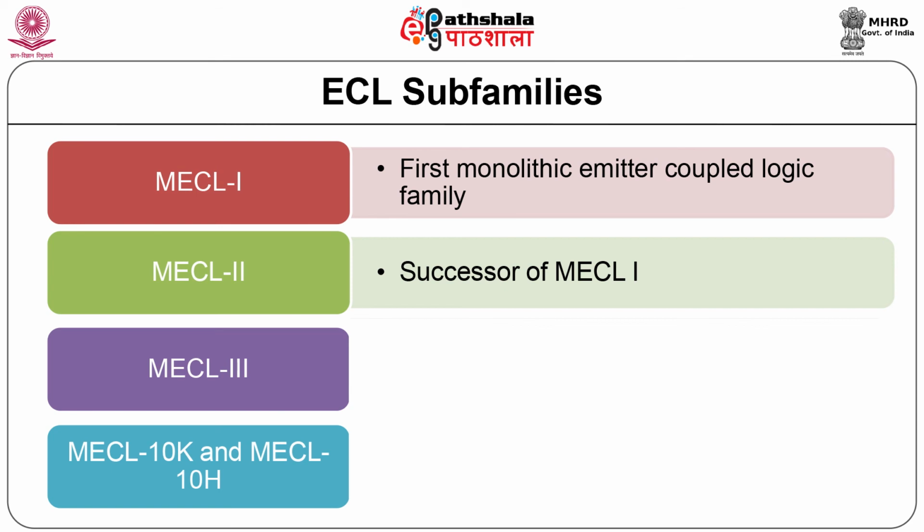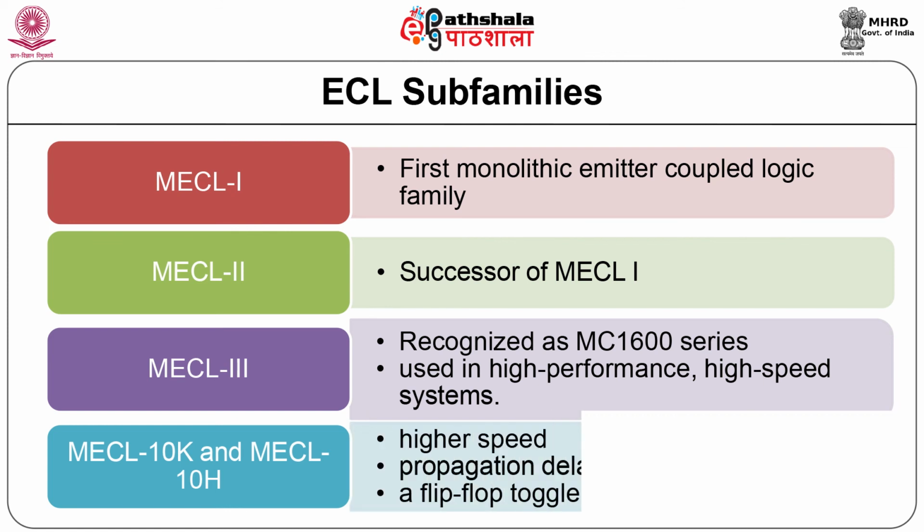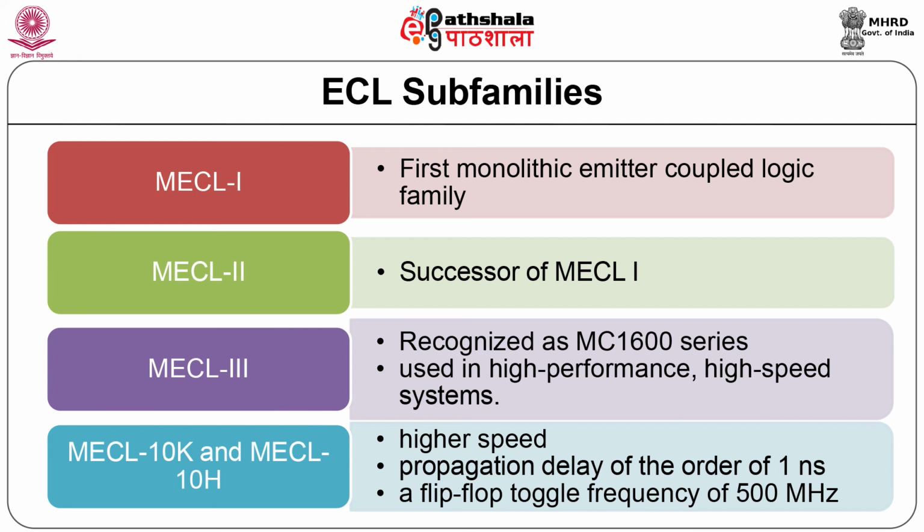Both these logic families have become obsolete and have been replaced by MECL3, also called the MC1600 series, introduced in 1968. Although chronologically MECL3 was introduced before the MECL10K and MECL10H families, it features higher speed than both of its successors. With a propagation delay of the order of 1 nanosecond and flip-flop toggle frequency of 500 MHz, MECL3 is used in high-performance, high-speed systems.